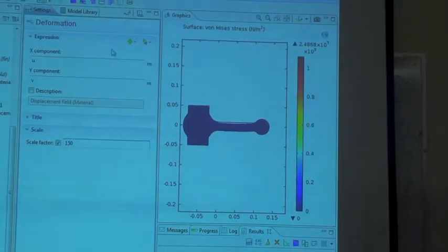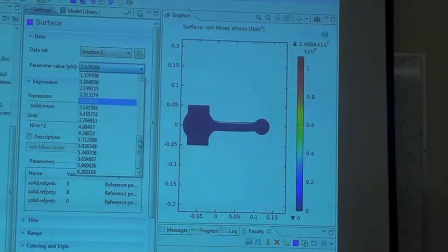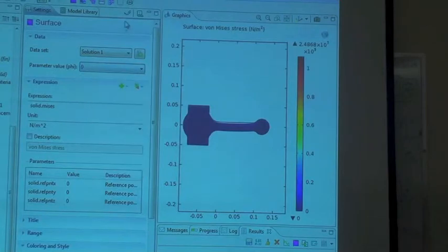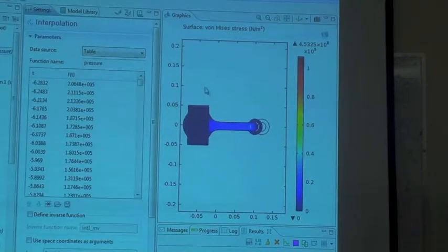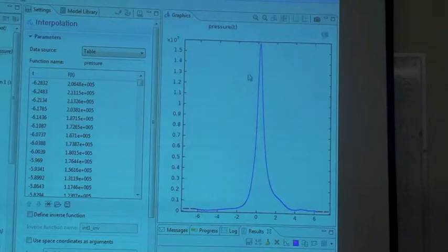So if we go through all the connecting rod angles, at 0 you expect it to be in compression, because the piston's at the highest. If you go back to the plot up here, at 0 you're getting a lot of axial loads from the pressure of the piston.